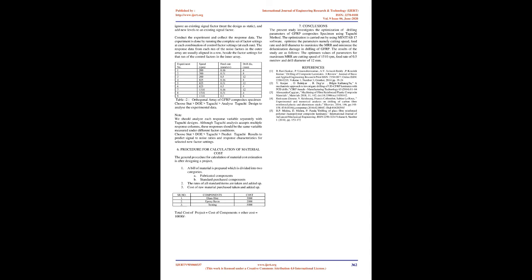We can also use Stat > DOE > Taguchi > Define Custom Taguchi Design to create a design from data that we already have in the worksheet. Define Custom Taguchi Design lets us specify which columns are our factors and signal factors. We can then easily analyze the design and generate plots. After we create the design, we can display or modify the design.